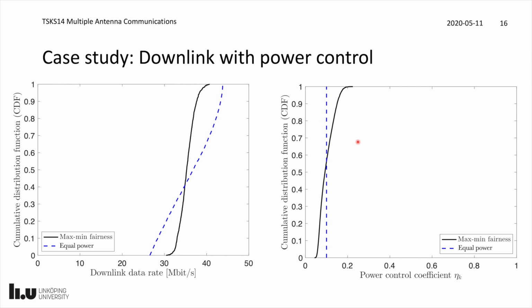But in the downlink, everyone is getting their desired signal and their interfering signal through the same channels. Some users are close to the base station, so they get these signals through a strong channel, and some users at far away locations, they are getting both the signals and the interference through a weaker channel. But we still cannot say that one person is going to transmit with 50 decibels more than the other, because then that is going to lead to immense interference for other people.